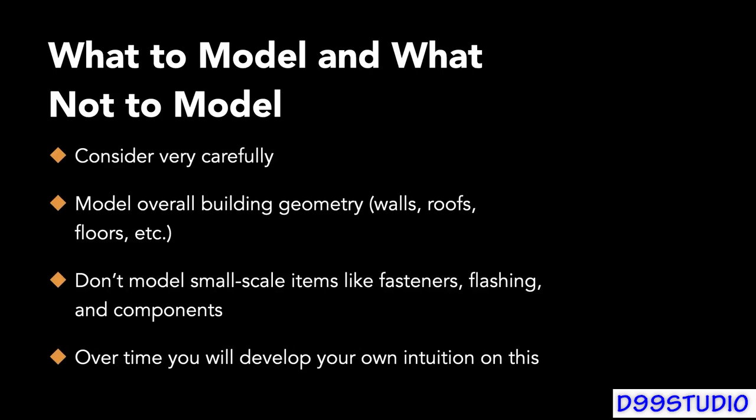So what we're going to be doing with the remainder of the videos here in this chapter is walking through the process of creating a hybrid construction detail. And we're going to approach it step by step. So we're going to start in the next video by creating a callout view of the actual live model, and then we'll begin supplementing that with two-dimensional detailing.